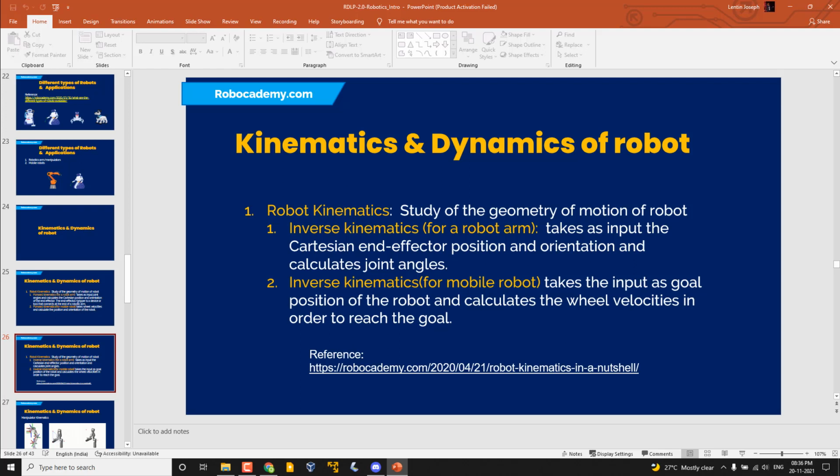For example, in the motor specification there is an RPM, right? Yes, sir. That is the maximum rotation speed the motor can do per minute. So only for the rotation we need to calculate. When it is going diagonally, first it has to turn and then go straight. For the straight part, it has to be the max velocity of the motor.